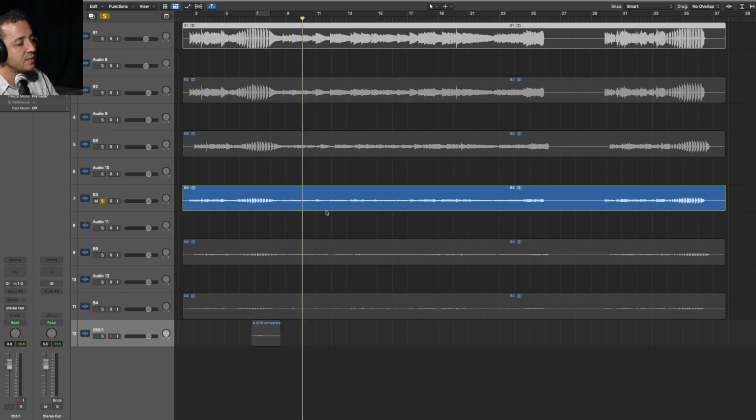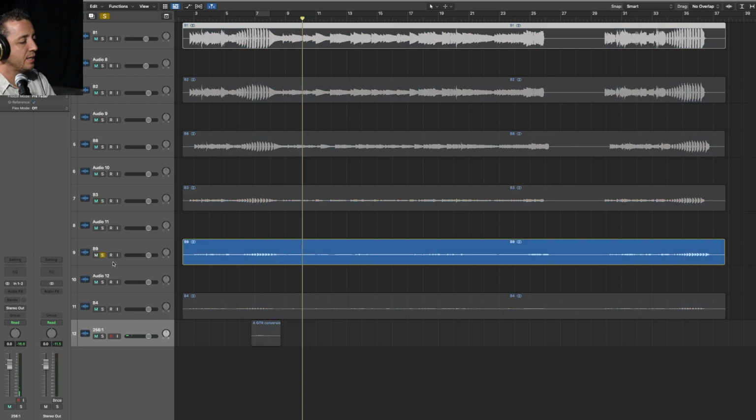This one here, this is what I would call pretty much an ideal gain setting. You're still way above the noise floor, even when they're playing quietly, and there's tons of headroom. And even if you set your gain a little higher than this or a little lower than this, this is good. And this one here is about the lowest setting you would want to go. This is still perfectly acceptable, but I just wouldn't go any lower than that.